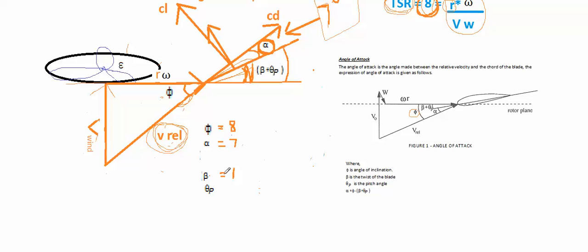So our wind turbine is happy now. It is exactly at an angle of attack of 7 degrees. That means we do not need pitch, because it's already twisted at 1 degree. So this is our design TSR, so we do not need pitching. This is for the design TSR, which was equal to 8. But see what's going to happen when the TSR will change.